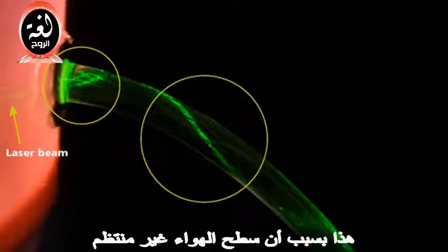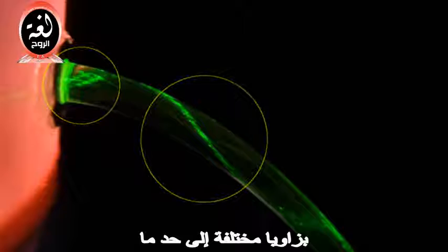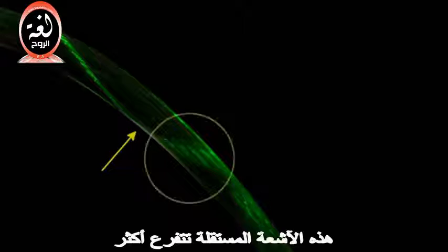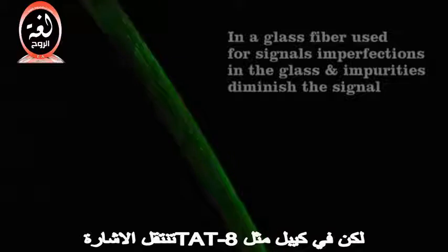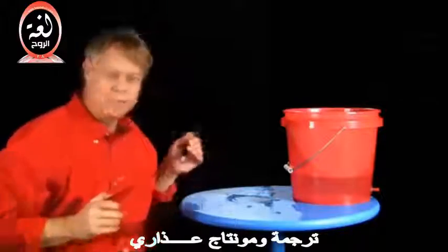That's because the interface with the air is uneven and the rays that make up the beam strike at slightly different angles. When that beam makes its second reflection, those individual rays diverge even more until by the time it reaches the third bounce, many of the rays are no longer at the critical angle and can exit from the sides of the stream. Here it happens in a few inches, but in a cable like TAT8, the signal travels a stunning 50 kilometers before it needs to be amplified. Absolutely amazing. I'm Bill Hammack, the Engineer Guy.